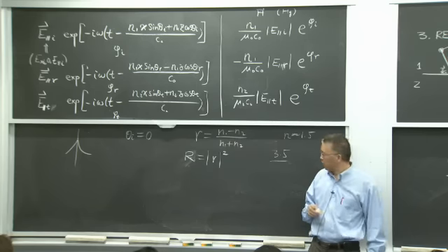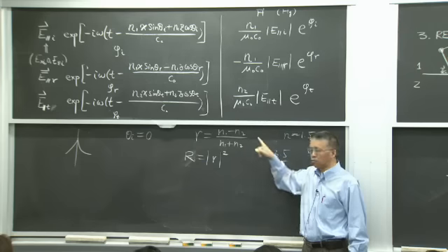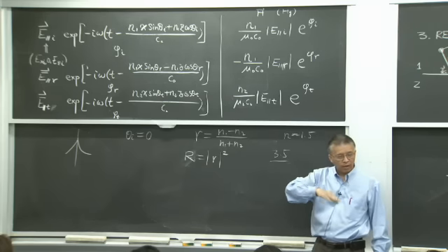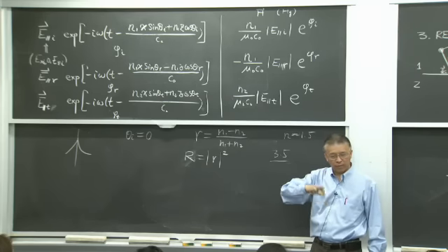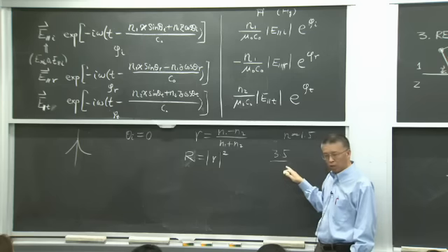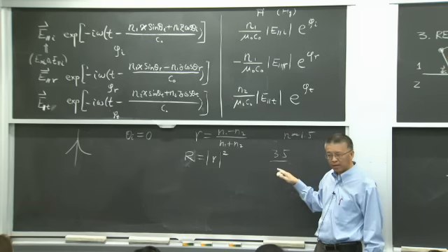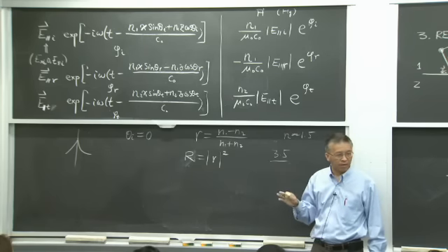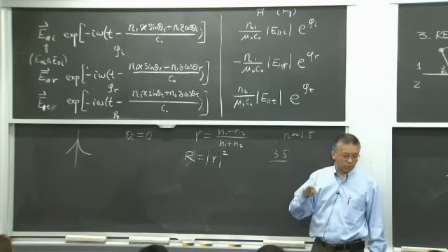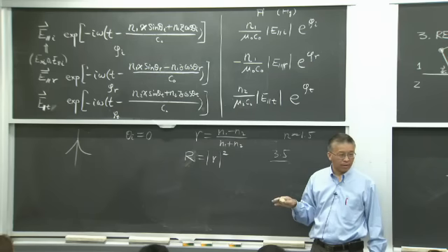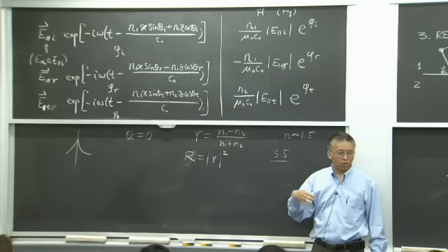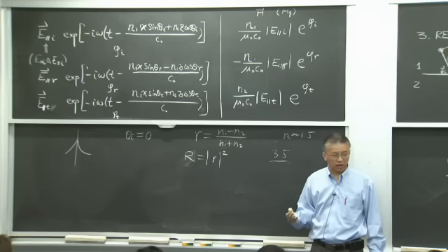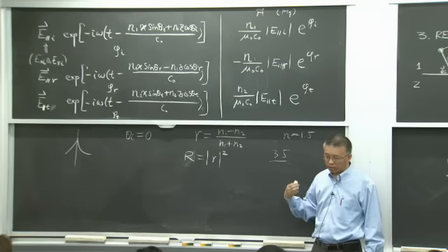right? So 3.5 minus 1, so for the silicon interface, how much reflection is 2.5 divided by 4.5, squared, right? 2.5 divided by 4.5, that's about 50%. 50% squared, 25%, right? So the silicon interface reflection is about 25, 30%.